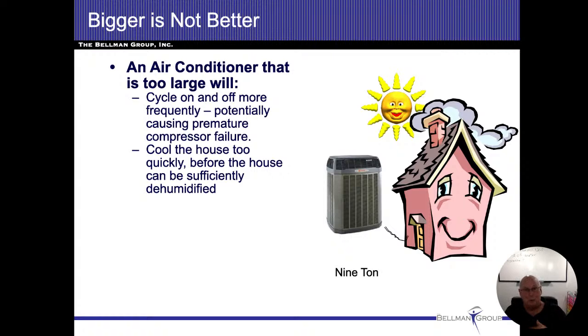Going back to my house, with a 2-zone system, my upper floor one on the hottest days of the year should be running pretty much consistently. And then rarely should the first floor one kick on. So the problem with large air conditioning systems is they cycle on and off very quickly, and that shortens the lifespan. The more they turn on and off, the shorter the lifespan is going to be on these things.